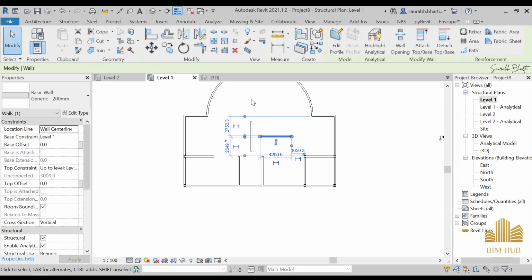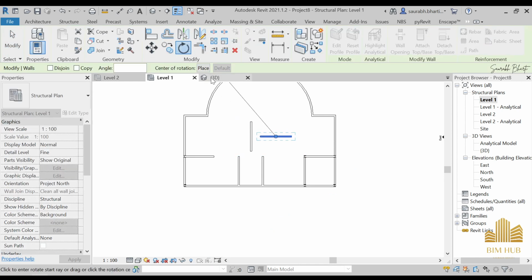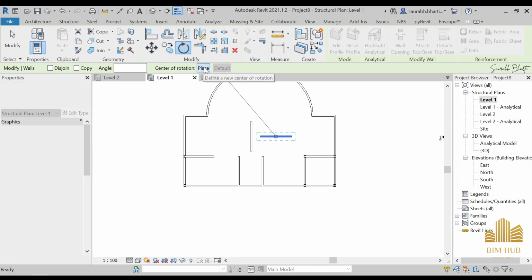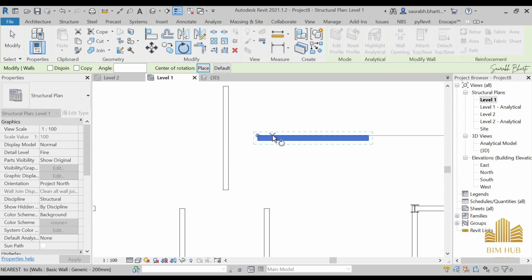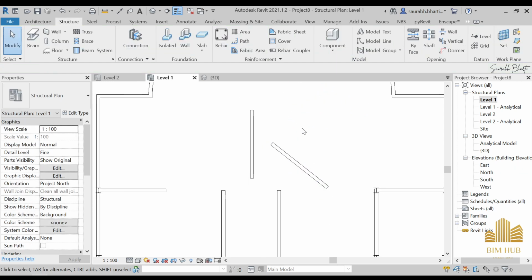Then you have an option, that is, if you again go to the rotate, you can rotate it by place. By place I mean, if you want to rotate it from this place to this place, something like this. So in the place option you first of all have to click on place. You can also give it a degree if you want to, and rotate it by any place. Like what if you want to rotate it from here to here only? As you can see, now you have fewer degree options over here. So this is also an option to rotate.